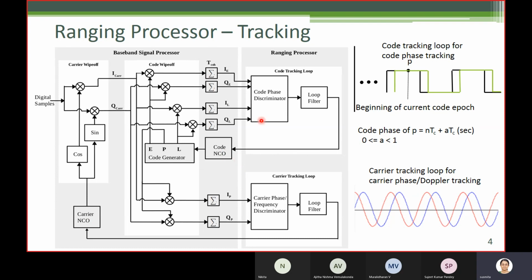And then under some assumptions, we will transform these feedback control loops to a block diagram representation, with corresponding transfer functions. So we'll basically have a simplified block diagram of these feedback control loops under some assumptions. And then in that feedback control loop with transfer function representation, we'll understand the operating principles of the loop filter at a top level, of course.